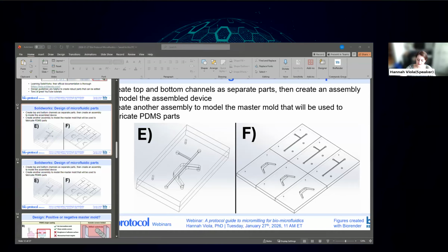You can definitely put microfluidics on a microscope. I had a custom setup where I did that. And again, it's just a consideration of the shape of your channel, how thick your device is going to be. You might want to specifically design it as a certain size and a specific volume of PDMS so that it's the same thickness every time. And thinner is better for microscopy. I think you can get some pretty good images, though. People more advanced than me have done really impressive imaging on microfluidics. And just one more advantage of micromilling: if it doesn't work, do a new design. You'll have it the next day.